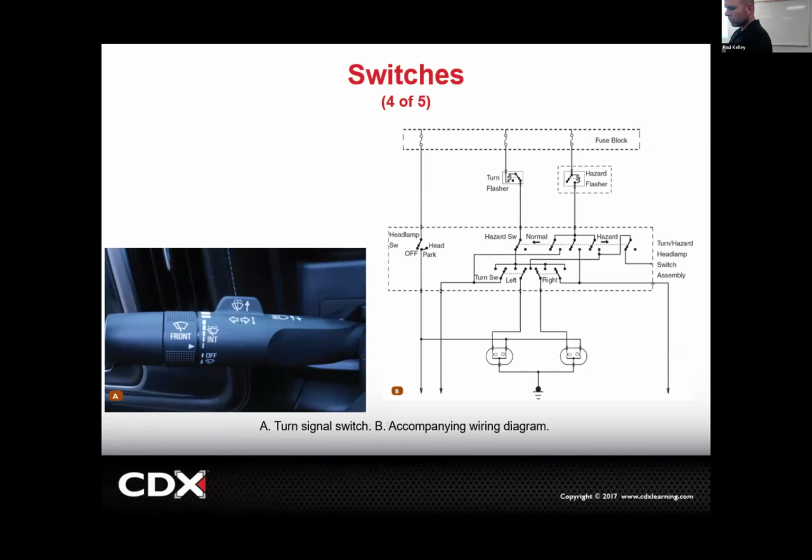So generally, no, you'd go to the connector. I don't have a headlight switch, but I've got this ABS unit. There's a connector right here. You could probe here to make sure you have voltage coming in, and then here to make sure you have voltage going out. But to get to that point, you have to know which wire is which and which location it's in so you can test them at the right point.